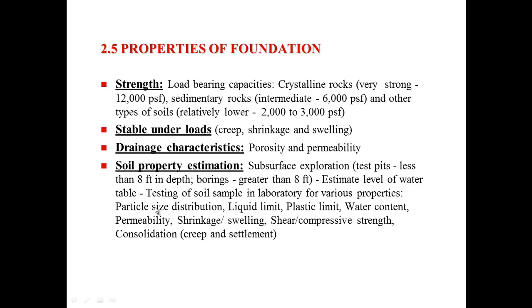Soil properties, your subsurface exploration, we talked about that. I will mention particle size distribution and the liquid limit and plastic limit. These are tested in the lab. The liquid limit is the soil's ability to hold water without becoming, at what point does it become unstable? In other words, it'll start flowing away or just slumping. The plastic limit is just the opposite. At what point, when we remove moisture, does it become hard and less pliable? So those are all things that we want to test into the foundation itself.